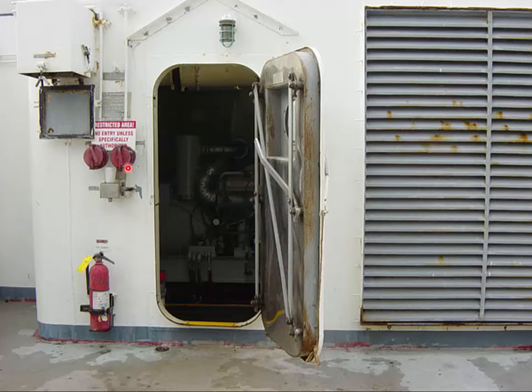Another thing is, in case it catches on fire, the space is CO2 protected. You do have this nice watertight door, but beside it you have a louver that is to allow airflow to the radiator. Unfortunately, don't think that because it has a watertight door this space is watertight. If a wave was to hit those louvers, it'll punch through them and it can flood the space. But that's part of its design, unfortunately.